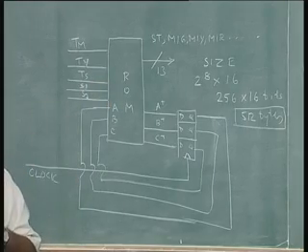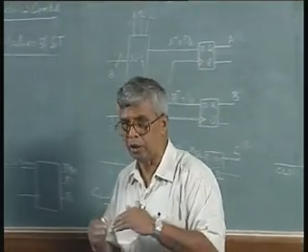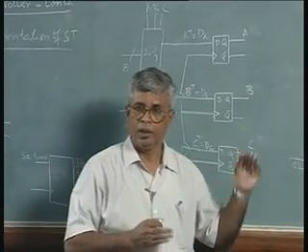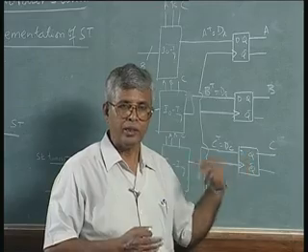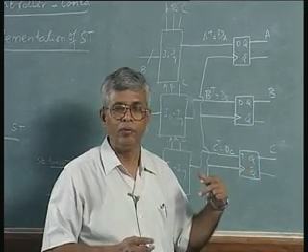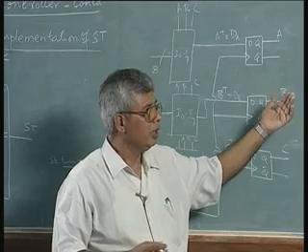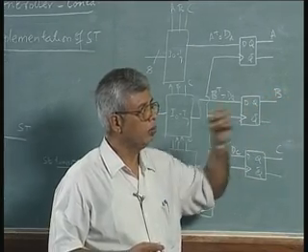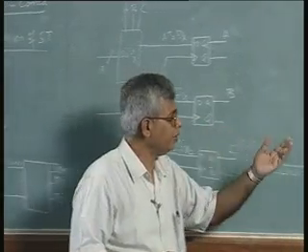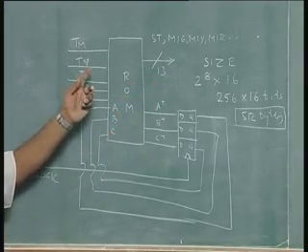It is very simple. My ASM chart will be expanded. In the ASM chart, we had only rows corresponding to a condition. There are 8 states, 0 0 0 to 1 1 1. Each of these states, if you expand, there will be a row for each condition. The truth table will have 256 rows, because there are 3 state bits and 5 conditions.